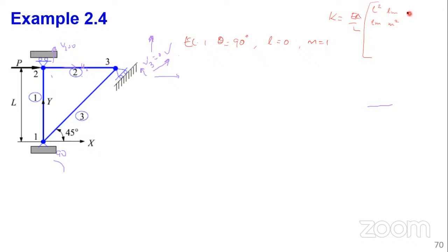The rest is minor diagonal negative: minus L squared, minus LM, minus M squared. And then the main diagonal is positive: L squared, LM, M squared. Okay. So once you have this, all that now remains is to substitute. So for element 1, we have that. Wherever there is L, because we know it is 0, that collapses to 0.